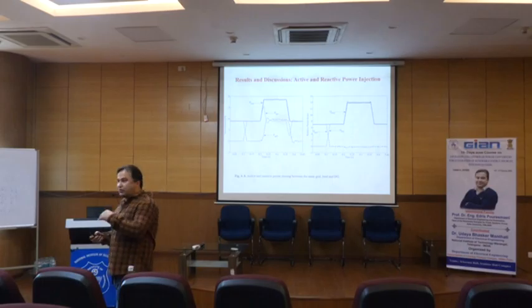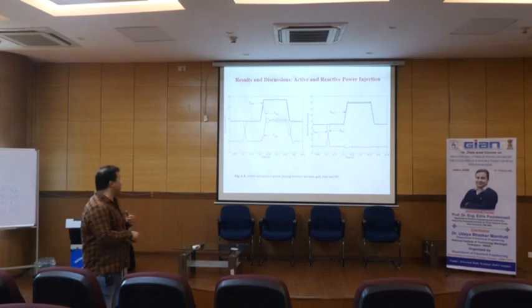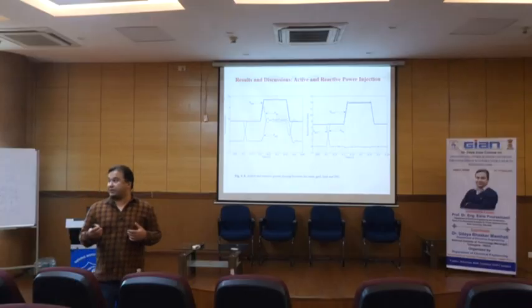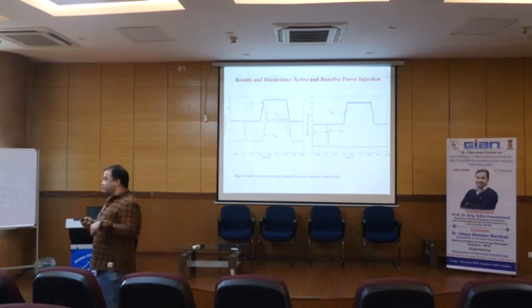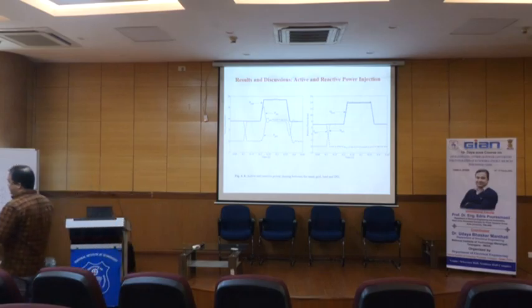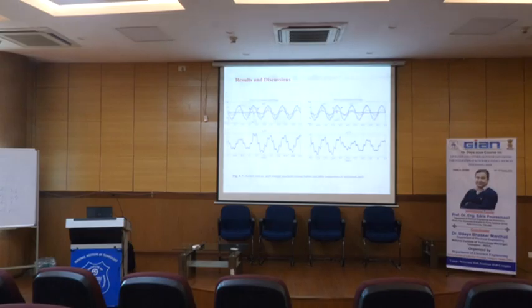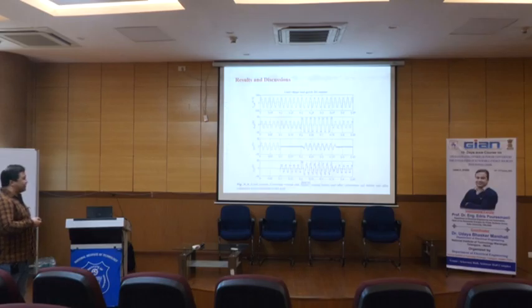If we have a strong grid, we cannot have that much. You see that it jumped from 10 to 15. So beside the filter and the other things that make the delay, it also provides some weakness from the grid which cannot damp it. And one thing, if we consider the impact, is here. Look, if you have this current, you see we have some notch here. Look at here, look at here. You see it? They have some notch here.